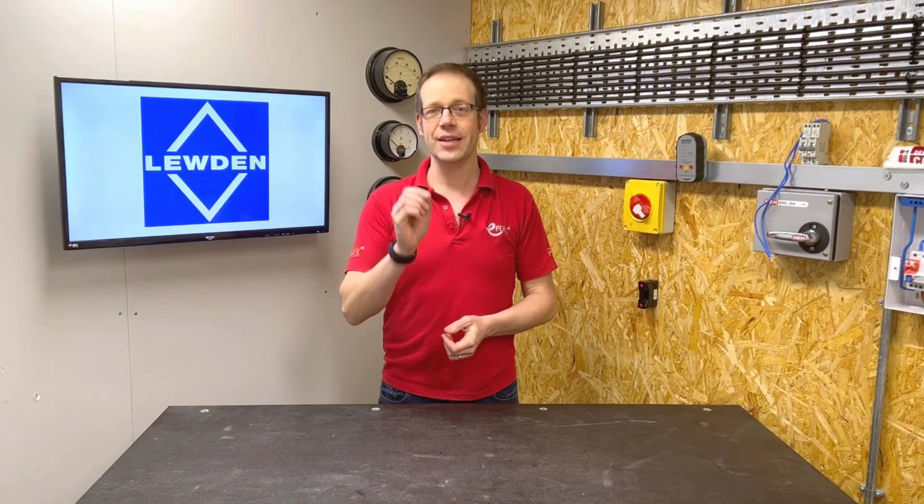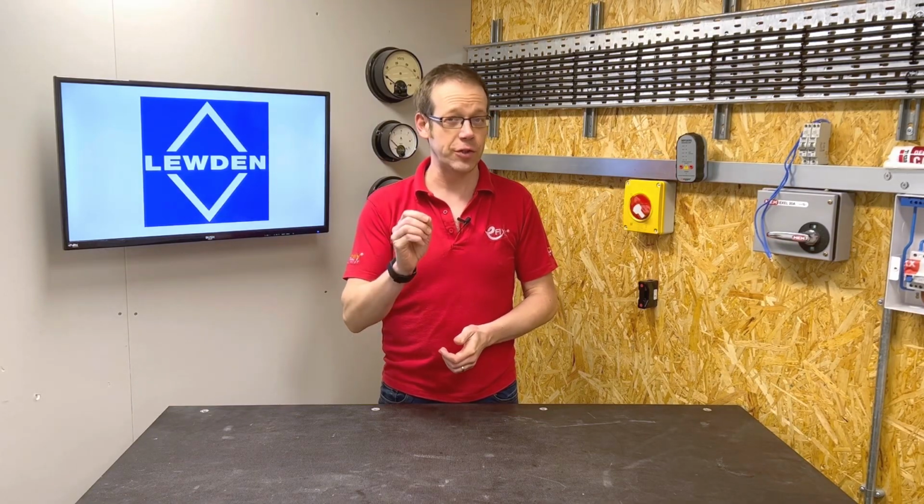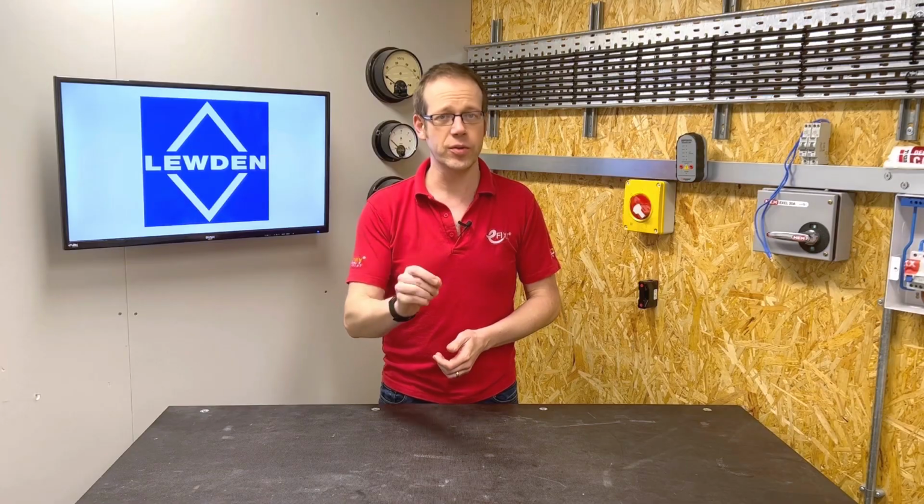RCDs have successfully made the transition from devices used in very specific circumstances for fault protection into their current position, offering additional protection for a vast array of circuits. Indeed, BS7671 now requires them in so many places and for so many circuits that it's hard to install a circuit in a domestic property that doesn't require their use.